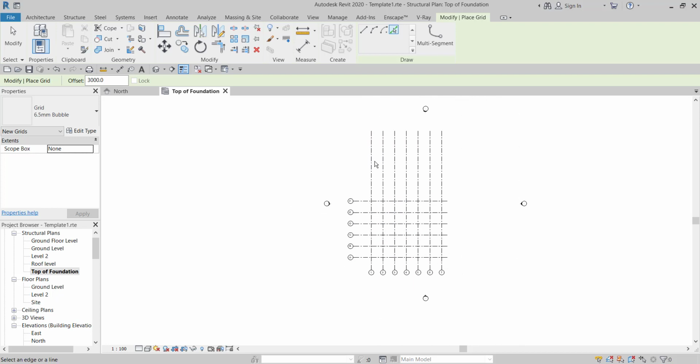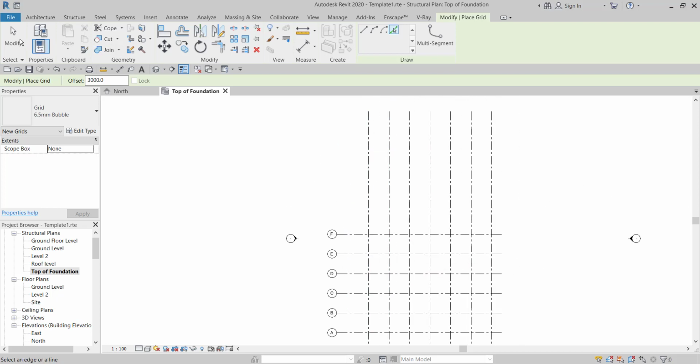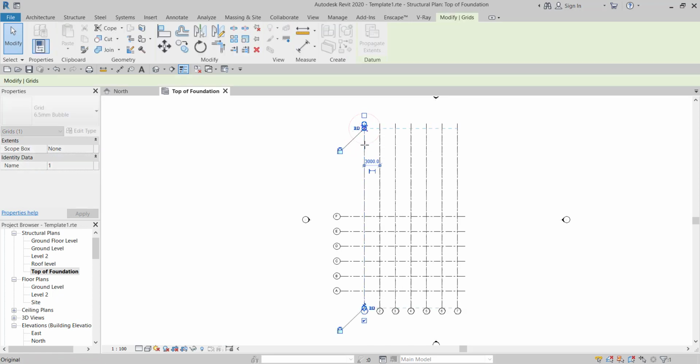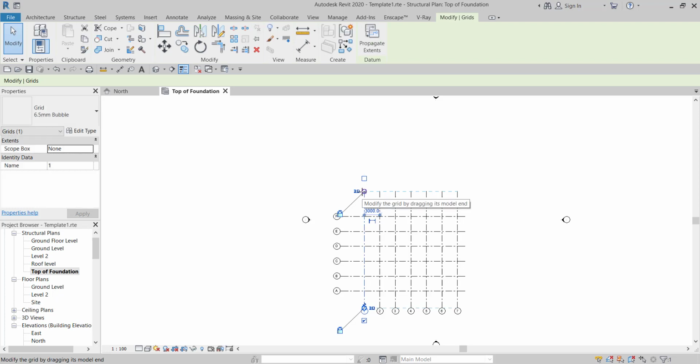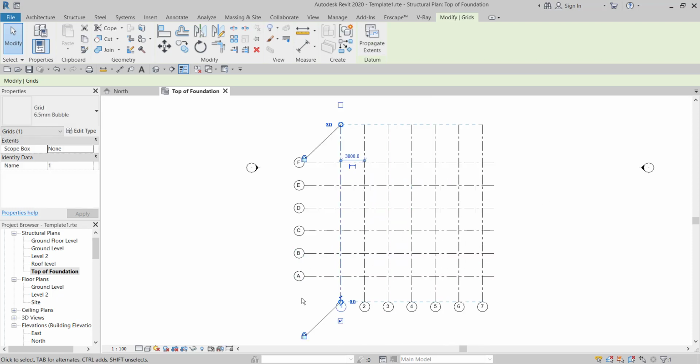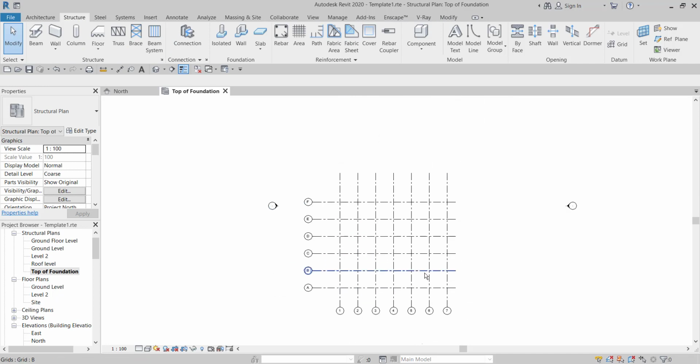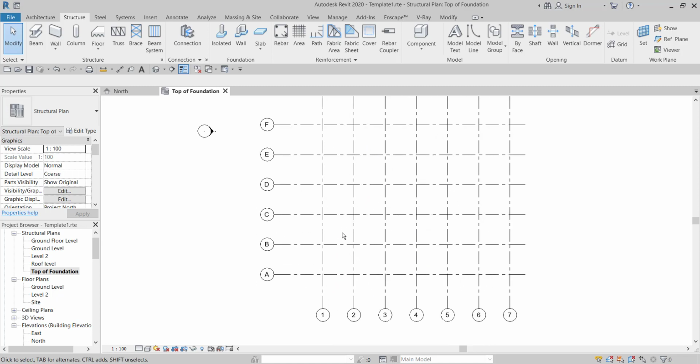So before an engineer can work on the top of foundation, the engineer will decide what the architect has done. But with this one, this is just a tutorial I am giving to you to help you build up your column bases. So after providing this, the next thing to do is to bring the size of the base. And the size of the base depends on the type of load which the structural engineer has imposed on the building, transferring from the beams to the columns, and from the columns to the column bases.